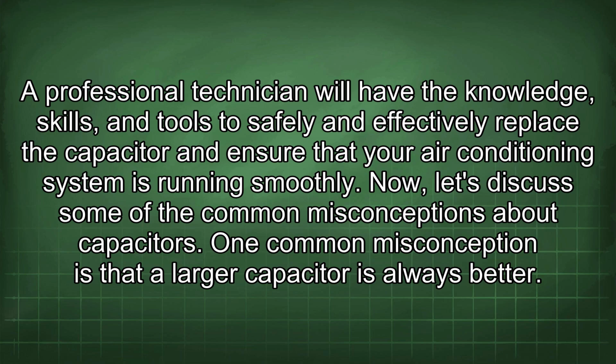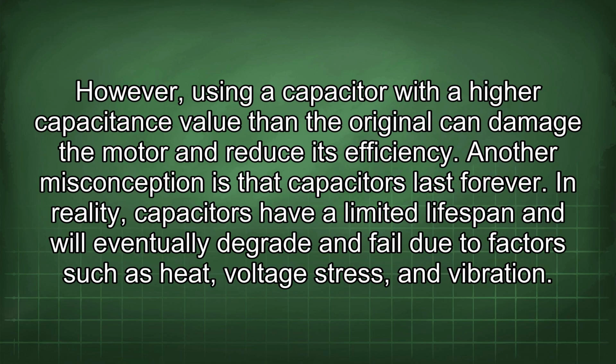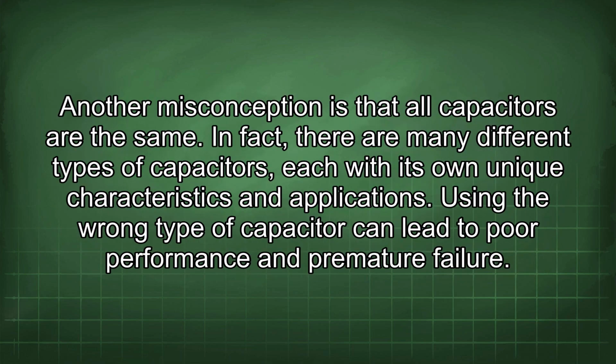Now, let's discuss some of the common misconceptions about capacitors. One common misconception is that a larger capacitor is always better. However, using a capacitor with a higher capacitance value than the original can damage the motor and reduce its efficiency. Another misconception is that capacitors last forever. In reality, capacitors have a limited lifespan and will eventually degrade and fail due to factors such as heat, voltage, stress, and vibration. Another misconception is that all capacitors are the same.